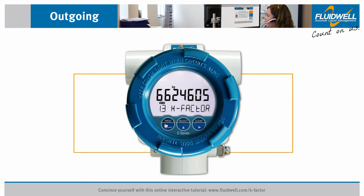The next step is to set the decimals for the K-factor. Press Select to go to Menu 1.4 K-factor Decimals. Press Prog to change this setting. In this example, our K-factor has 6 decimals, so we have to set the K-factor decimals to 0.000006. Press Prog to store this setting. Press Clear to go back to Menu 1.3 K-factor. You will see that the decimal point has been set and the K-factor is now 6.624605.